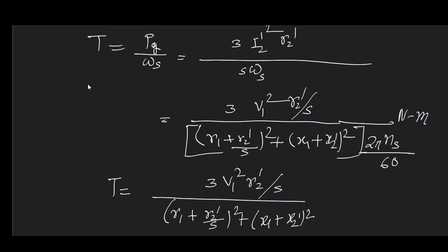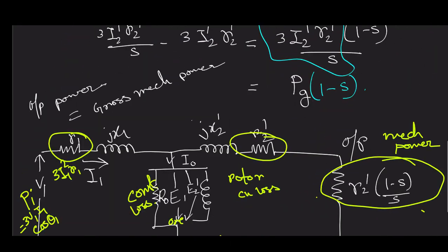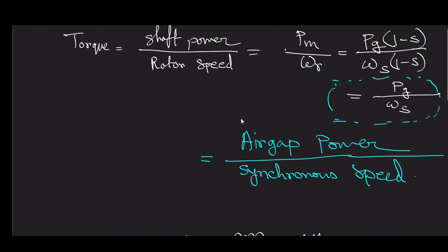Because torque is air gap power by synchronous speed, and synchronous speed depends on your stator structure and input frequency.